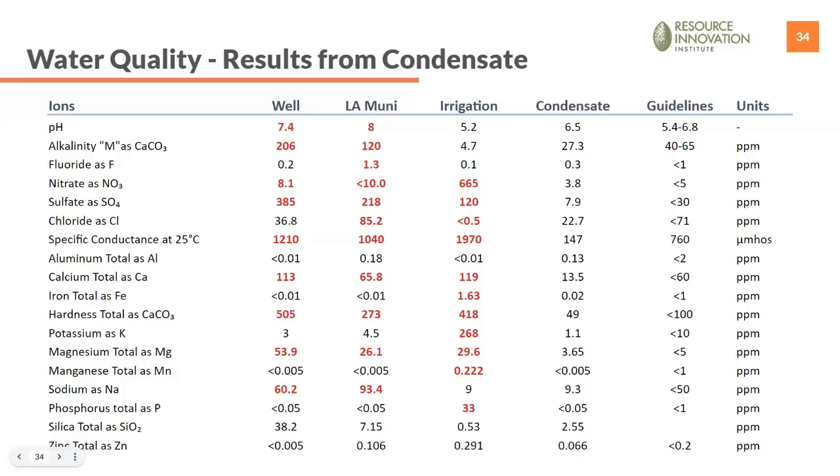The water quality is very good, and it can be used directly in your irrigation process, or it can be used to dilute your incoming water and reduce some of the bad ions in that conductivity water, or in that makeup water. So if you can reuse your condensate water, it's a good, clean source of water, and an excellent source to minimize the impact of these ions and high hardness. Next slide, please.